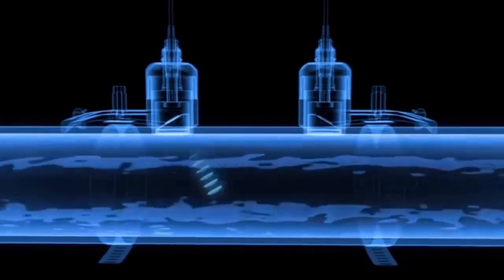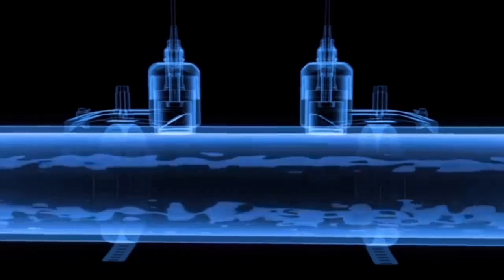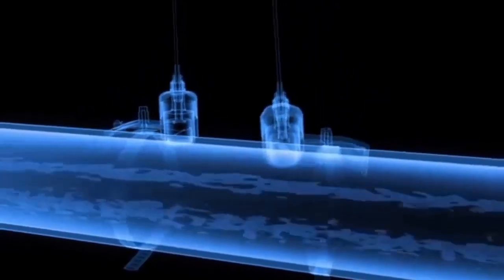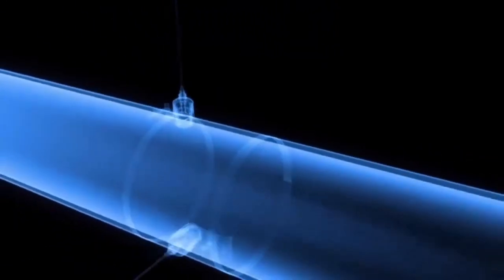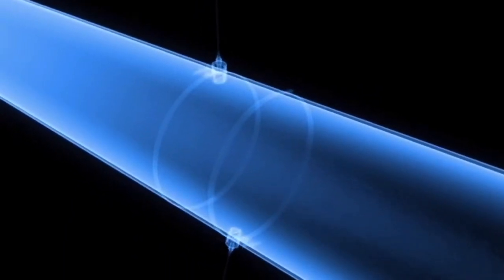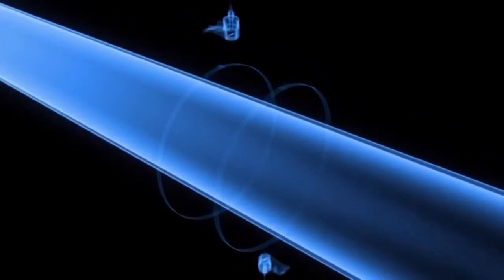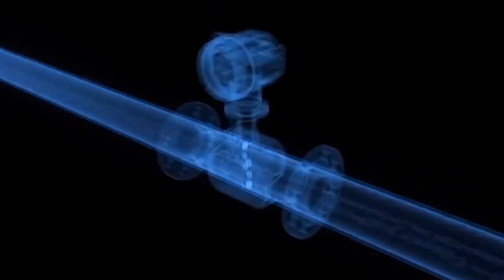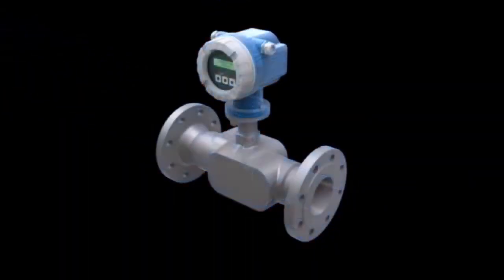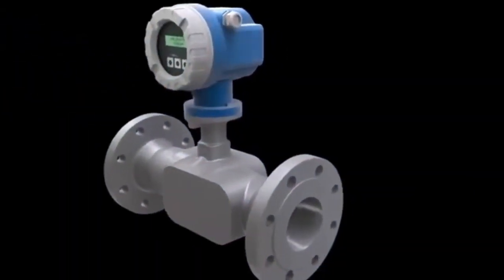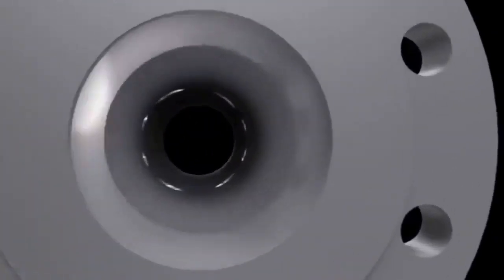This signal continues through the fluid, is reflected on the upper side of the pipe wall, and is measured by the second sensor. In this example, with the two traverse installation, the clamp-on design is unique because flow rate can be measured in very large pipes up to 4 meters in diameter. This possibility increases the area of application, for example in the water and hydroelectric industries.